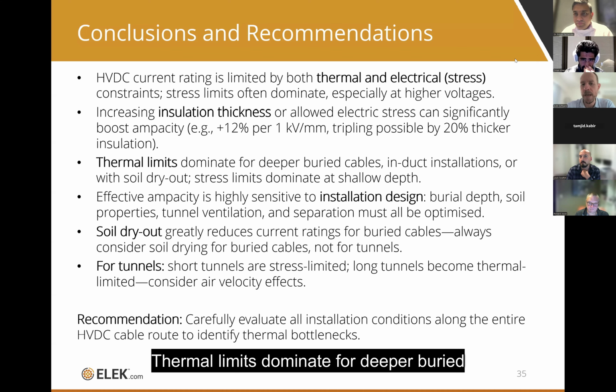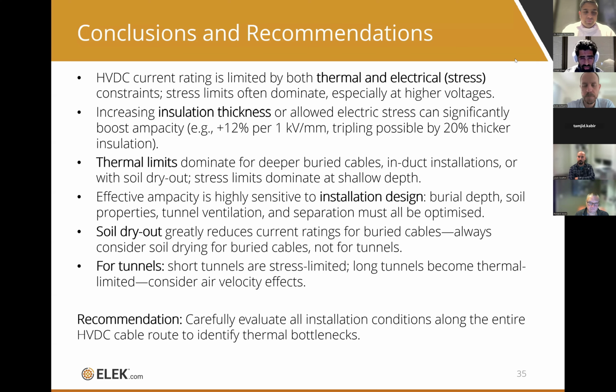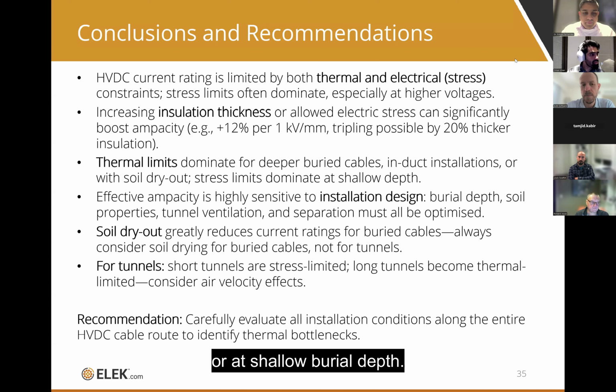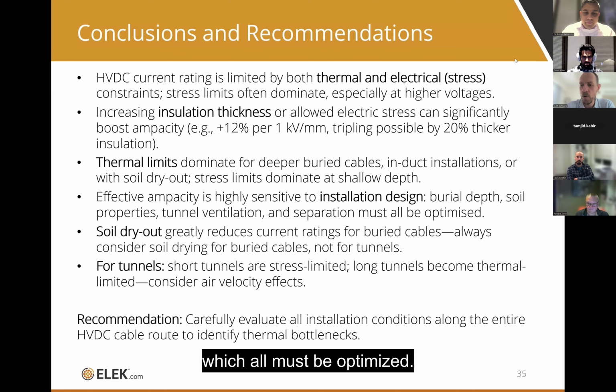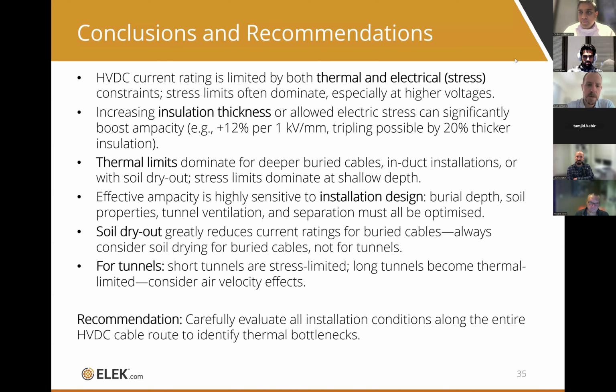Thermal limits dominate for deeper buried cables, in duct installations, or where soil dryout occurs. Stress limits dominate usually in air or at shallow burial depth. Effective ampacity is highly sensitive to installation design such as burial depth, soil properties, tunnel ventilation, and separation, which all must be optimized. That's pretty typical of AC or DC.